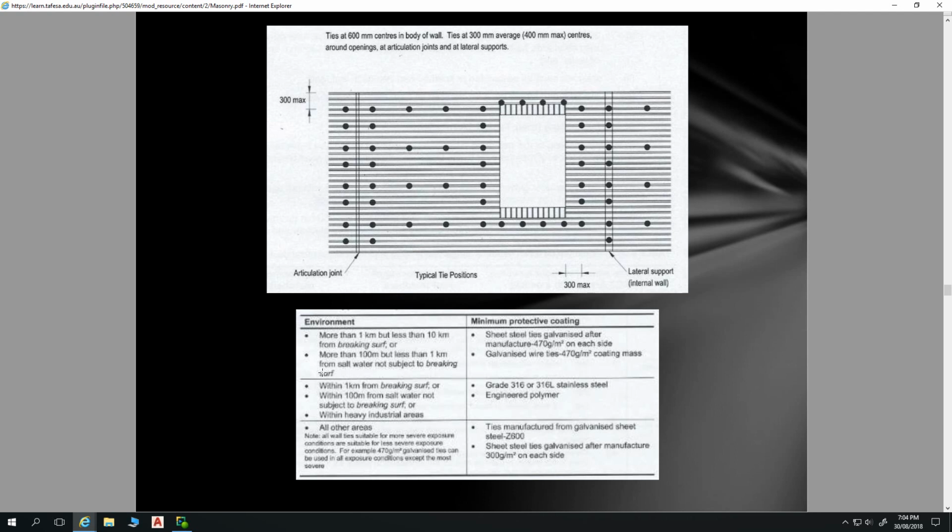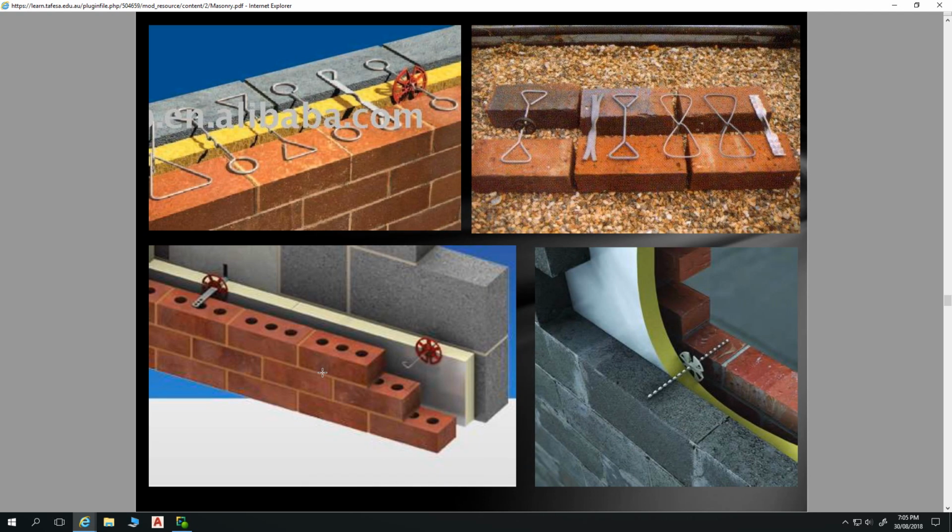So your brick ties, these ones are at 600 centres, so 600mm vertically and 600mm horizontally, so that corresponds with each stud. Then at your windows, they have to be at 300 centres max. Typically they're going to be less than 300 centres max because you've got your jamb studs right near your window. So you have your jamb studs in here, and then your windows fixed in to those jamb studs.